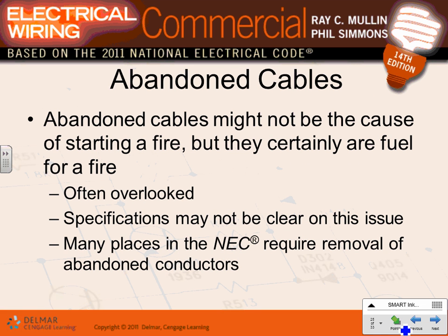A couple of things about abandoned cables. What do you do for abandoned cables? This is kind of shifting. You're supposed to remove abandoned cables, high voltage, low voltage, and so forth. We do this one in the specification. A lot of engineers add this one if they're remodeling: abandoned electrical equipment and cables shall be removed. Right in the specification if you're doing remodeling business.